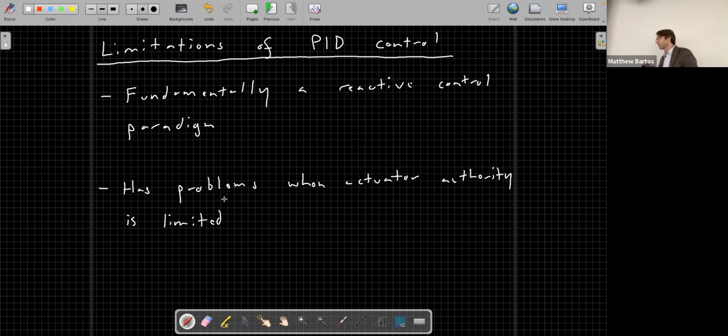Let's say you're a flood control operator, so you're operating a dam, and you want to release water from the dam to make sure that the system doesn't flood. PID control won't perform particularly well here because your control strategy only has access to the current state of the reservoir, for instance its depth and its derivatives and integrals over time.